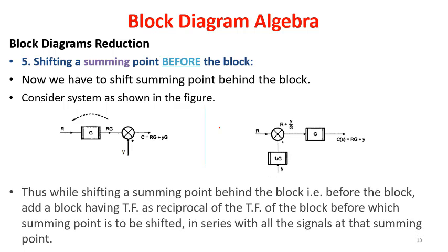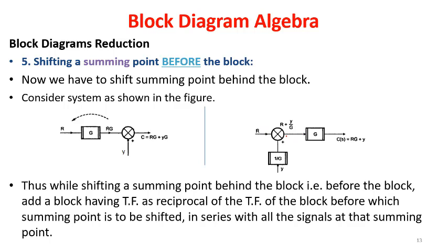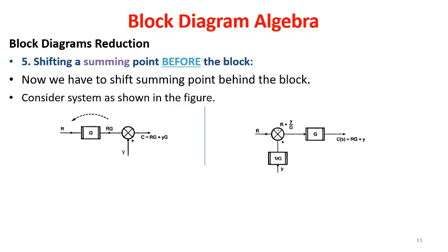Now, thus, while shifting the summing point before the block, we bring the reciprocal of the forward block in series with the summing point.